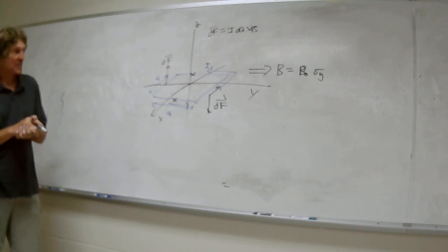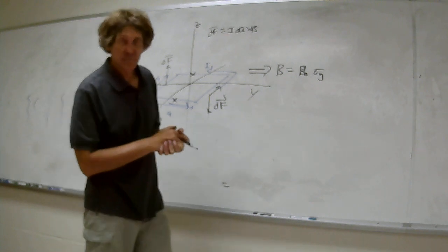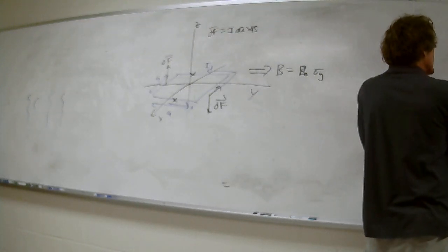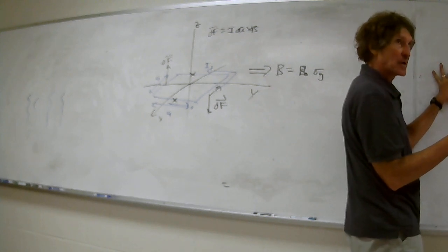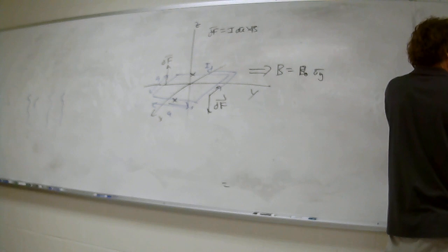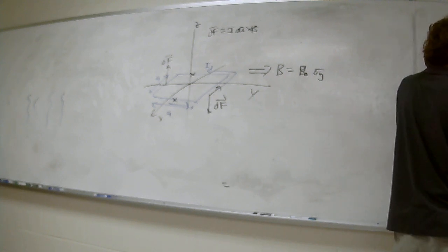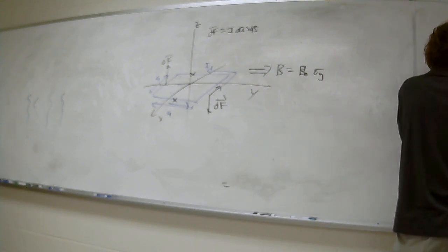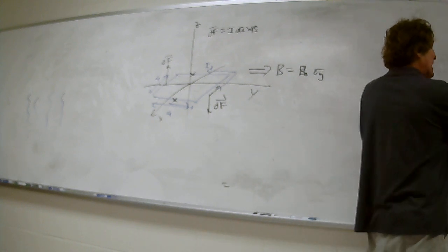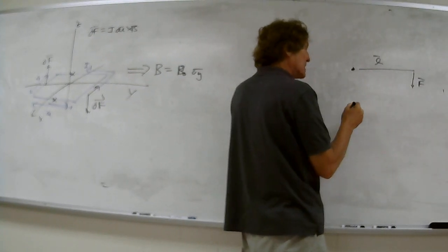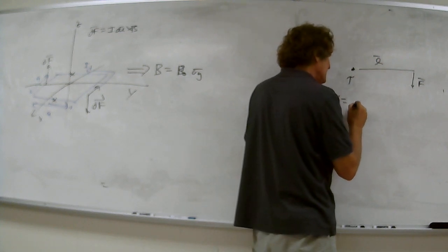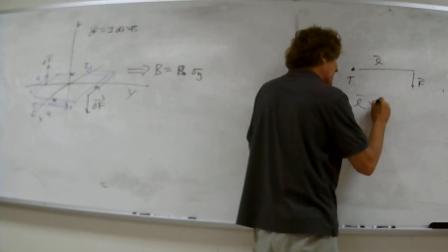Now, there's something called torque. Y'all remember torque in physics? Torque is about a point, called an anchor point, and I have something of length L around it. You should do this with vectors, but I'm not going to. I put a force down here, F, and it creates a torque around here. I'm going to make L a vector and F a vector, and torque is equal to L cross F.